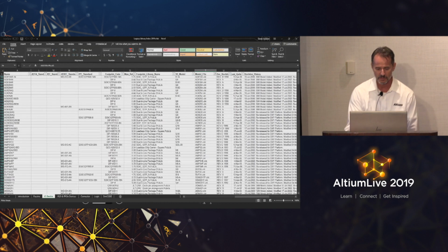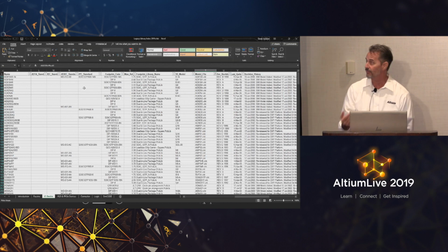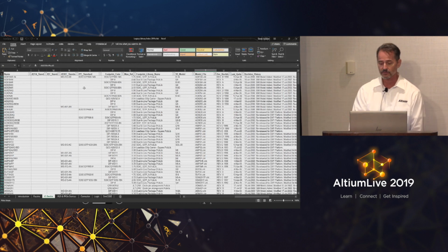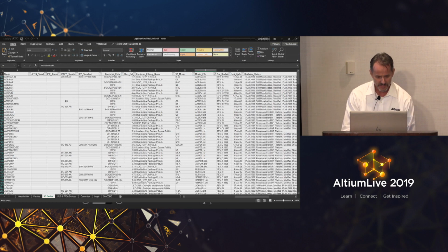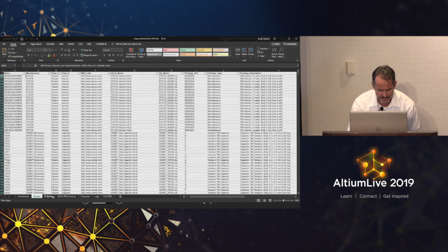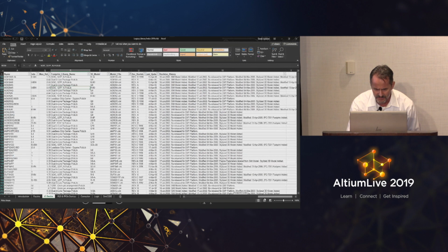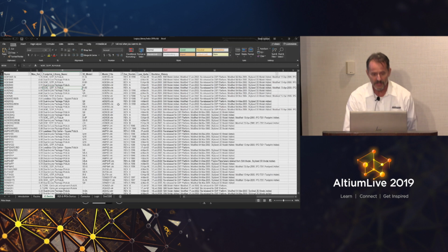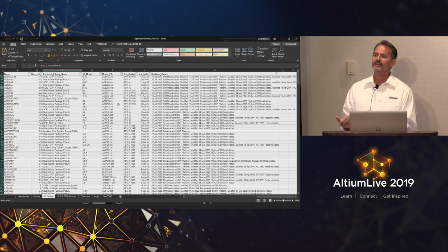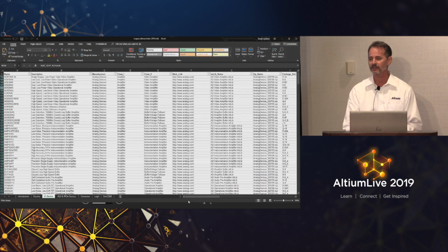There's a lot of them, and it'll show the last corresponding integrated library with that. And so you can either download the library itself, and it's divided. You have your passive ICs here, and the integrated library is listed here, and it'll show the model library. Now, our integrated libraries have the schematic and the model and everything all packaged into one library. So when you get the integrated library, it'll have all of the components inside of there. If you wanted to break them out, you could extract the sources to get access to the actual libraries themselves.